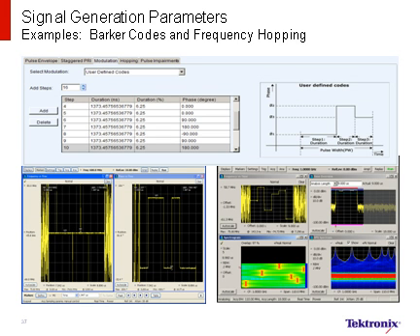The user interface provides tabular inputs for common pulse parameters with graphical descriptions of the definitions used in the terms. This is shown in the upper graphic. Within minutes, you can create complex Barker codes, polyphase codes, ideal chirps, and hopping frequency patterns that are directly synthesized by the AWG. In the lower left example, we're creating a Barker code, while the measured frequency versus time plots are shown on a spectrum analyzer. The lower right example shows a frequency versus time overview, spectrogram, and the DPX spectrum of a synthesized frequency hop signal.